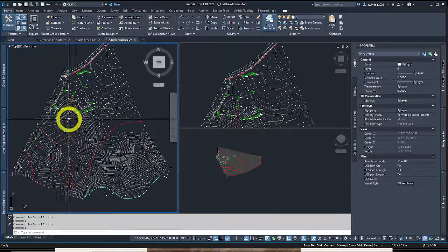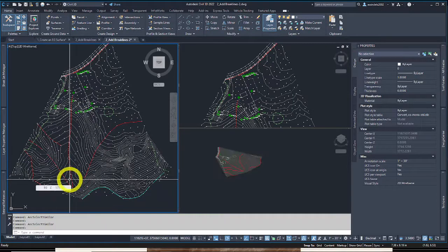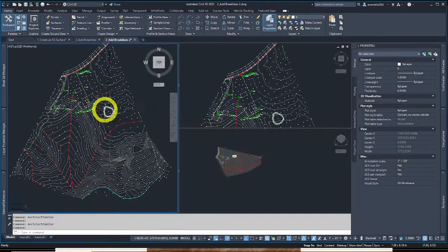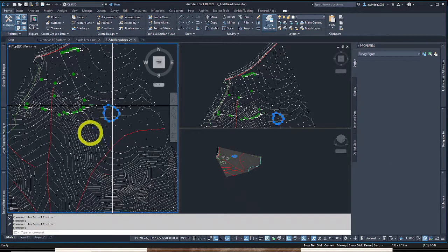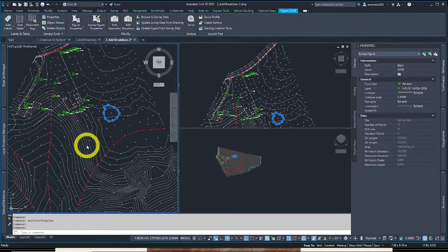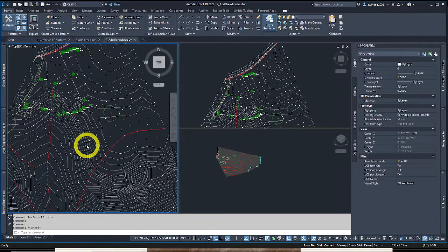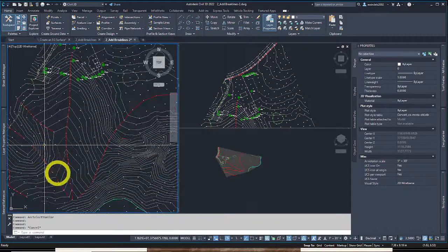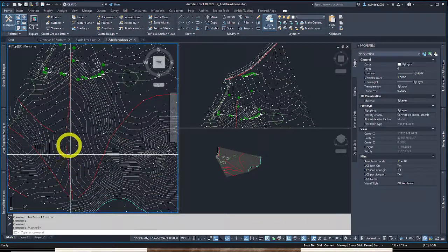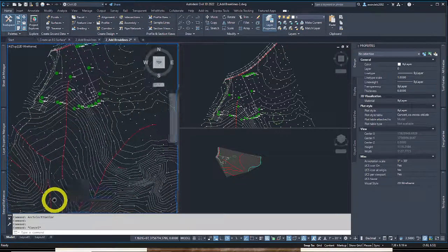So there they go. They broke on the surface. And on the bottom of page 73, it's just explaining a little bit why we didn't add the fence and the edge of tree line, because they're not defining features of the surface. So we're going to continue on to page 74, which starts by saying what I already mentioned. You can see how these swales and these contours are now better formed because of these break lines we added.